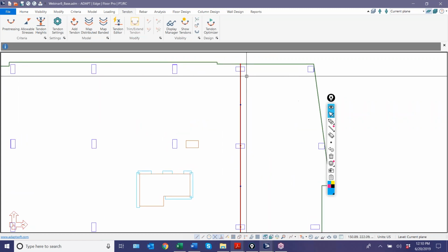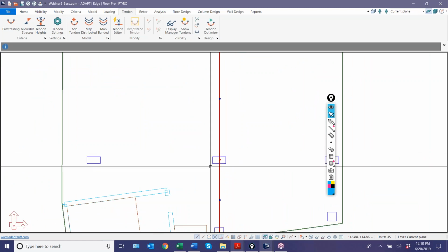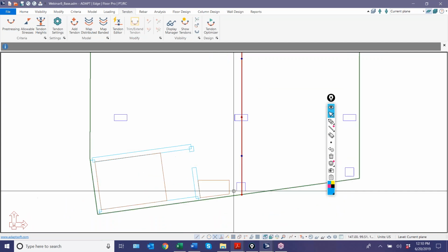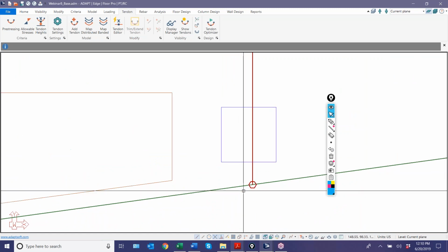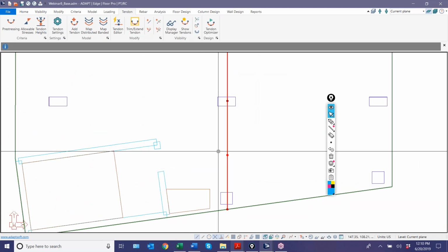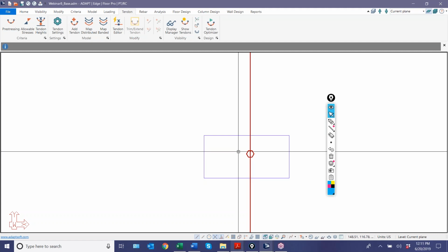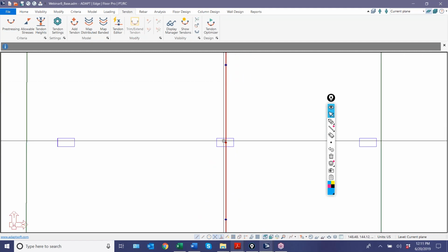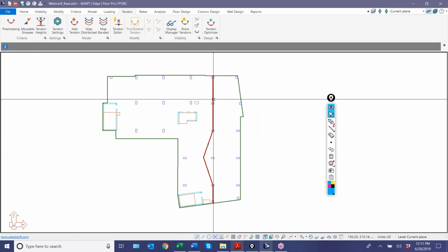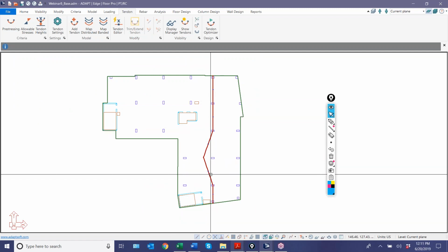So there are a few characteristics graphically that represent what's happening with the tendon. The program has control points and static points that you don't have the ability to modify graphically here. The control points will always match the color of the tendon. So for example, this endpoint, the start and end points, are always control points. They are the anchor points. The interior snap points are the high points. The snap point here, you can see this is a red symbolic dot there. The same thing here at the columns. I could select this and I can move these points. When I move this horizontally, this is linearized. You can see there are two spans and then a span here, and there's no horizontal curvature to this cable.